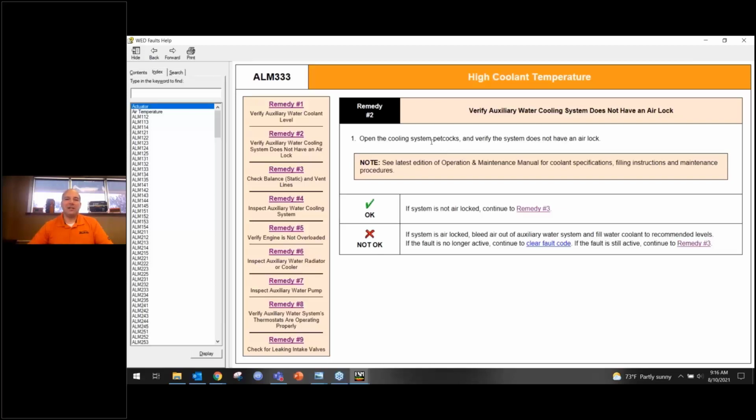On early systems, or as the engines are manufactured, we leave a petcock, like you would see on the bottom of a radiator of a car. It's just a little thread that goes in and out in order to vent things off or allow you to drain things out. We put them at the high points on the engine. Now, in the older manuals, it said you should open and close those once per day to make sure that you don't have any air getting into the system.